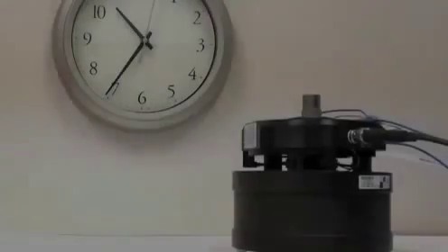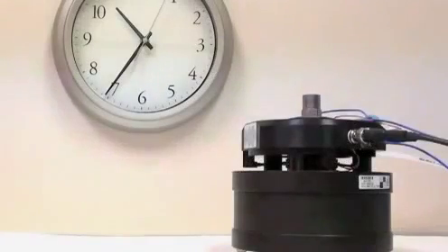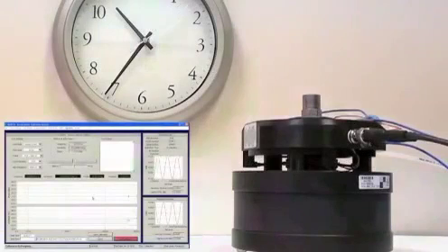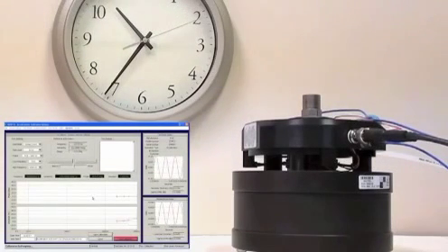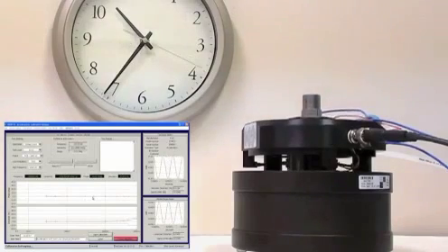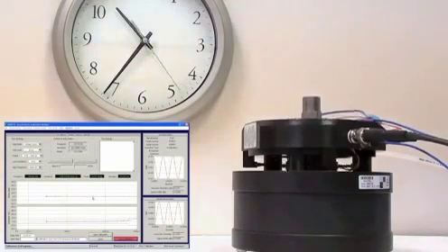is equal. A typical sine calibration is performed by exciting one individual frequency at a time and using the known sensitivity of the reference standard and the voltage output of the two sensors to determine the sensitivity of the sensor under test. Alternatively, multi-sine or broadband excitation may also be used.